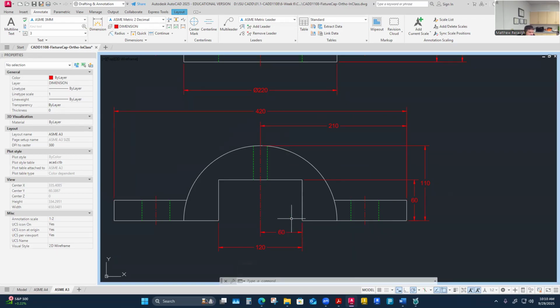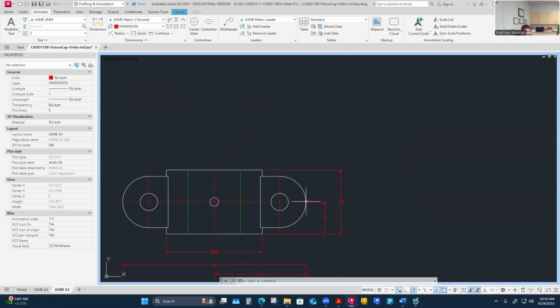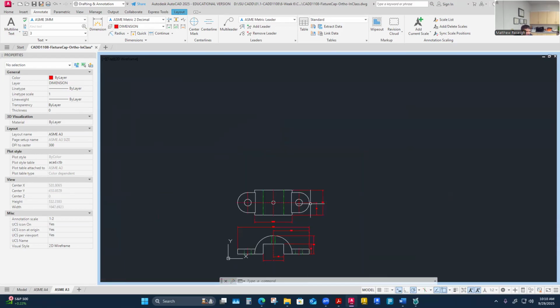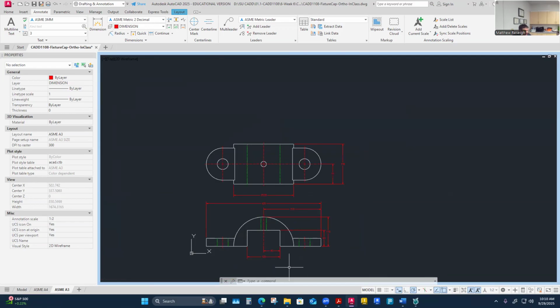Center lines are really powerful. Just remember that. When in doubt what to dimension to, think of a center line. Especially if I have radius features and things that don't have a lot of surface. There's just not a lot of surface associated with the true right side of this part. It immediately goes away from me in a radius. So the center line is a better datum choice because its surface is so small and immediately curving away.